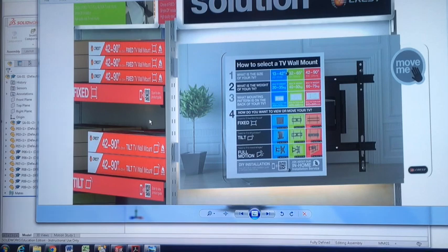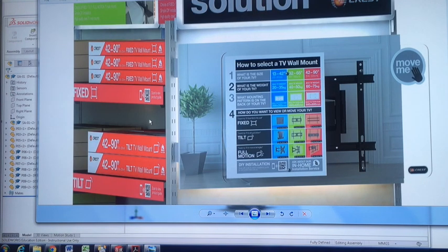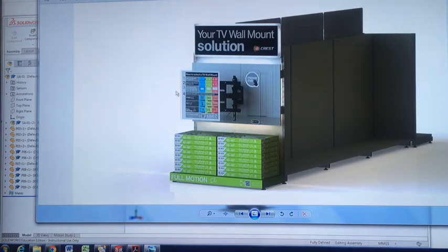With materials, when you're rendering, even though a material on the side says aluminium or it says glass, sometimes there are better materials to be used if you're trying to show a certain appearance. From experience, what you'll learn is it's all about how it looks in the end result. So in certain lighting situations, one material, one type of metal might not look as realistic, or as good, as another type. So there's nothing wrong with changing it around to get the better result.